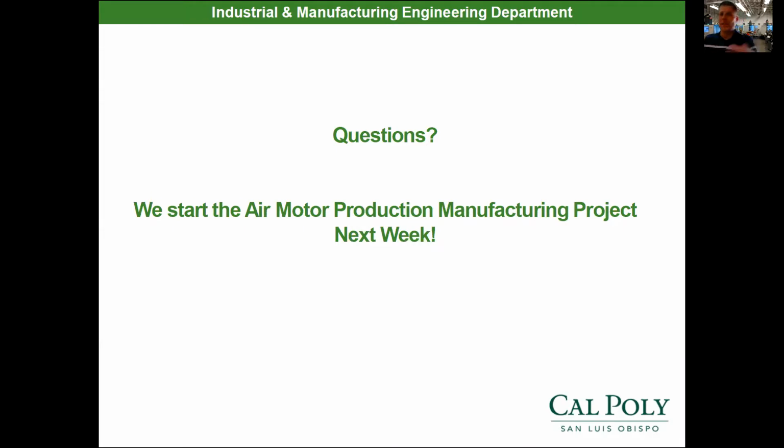We conventionally machine it first, and then we go ahead and use the abrasive processes to get us down to that tight tolerance. Or we conventionally machine it to the right size, we heat treat it, and then after heat treatment, we use an abrasive process on it to remove a small amount of material to get it back into the correct size, because heat treating will cause it to twist and change to all different sizes.